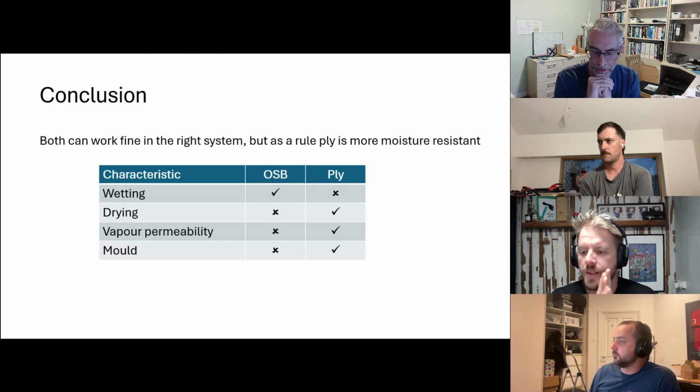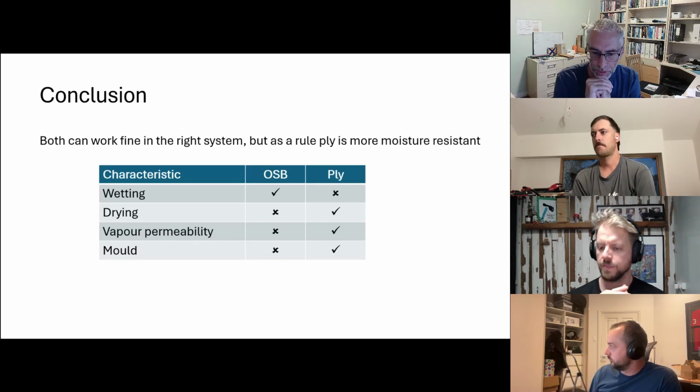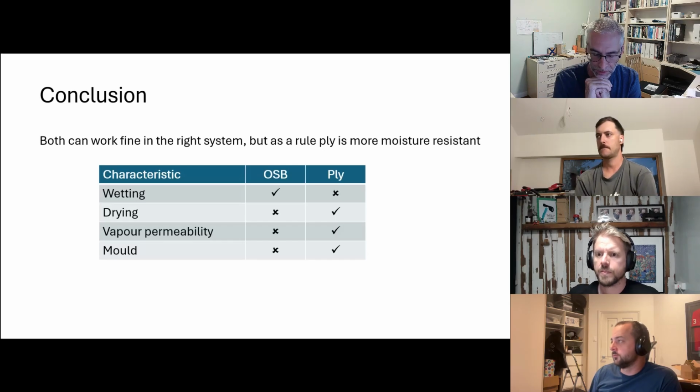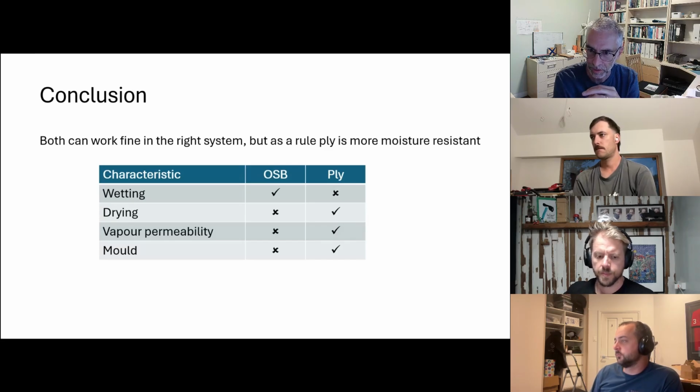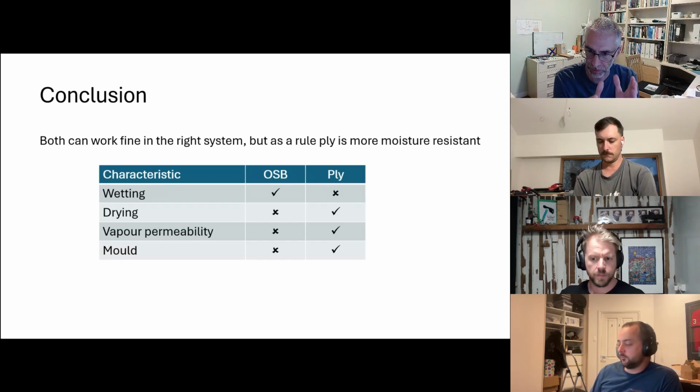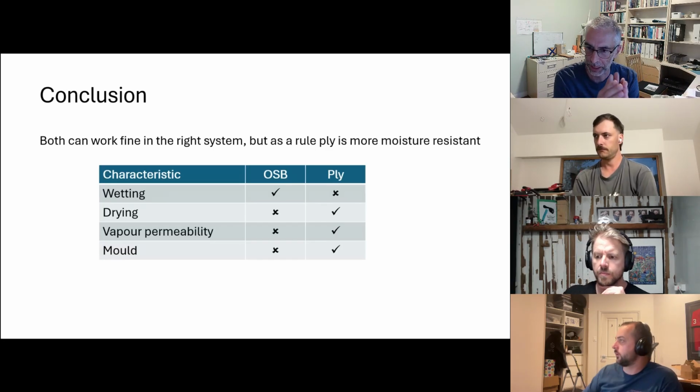Yeah, fully agree with that, Hamish. It just makes such a structurally rigid building if you just sheath the thing up. You do change the vapor permeance of the assembly. And this comes to things like these peel and stick membranes. The other way we measure vapor permeability is something called an SD value. It's closer to what I would consider an R value in a thermal sense, because it's a function of both the material property and its thickness.